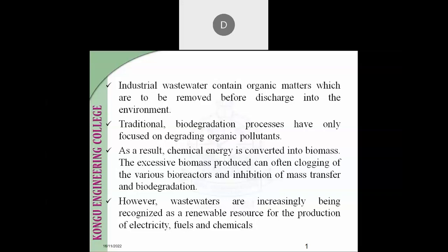At present, people are mostly concentrating on the preliminary, primary, secondary, and tertiary methods. If you take industries, for example the textile industry, they take the textile industry effluent and add calcium chloride, alum, and other electrolytes such as polyaluminum chloride (PAC).